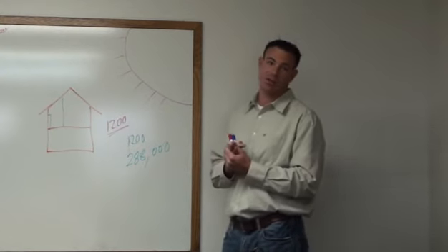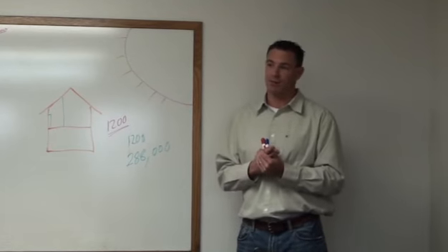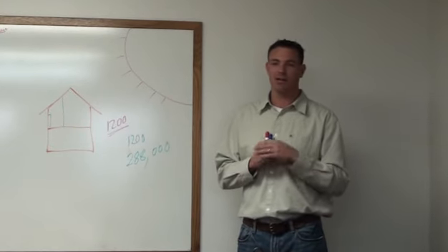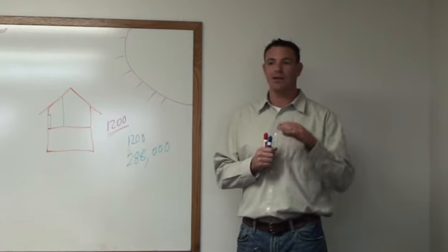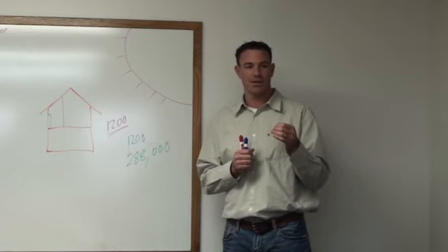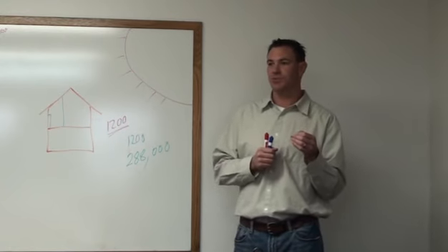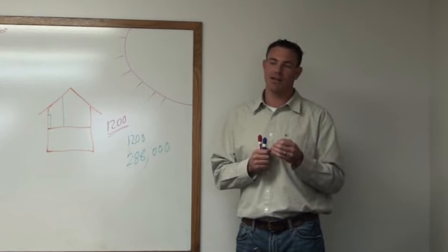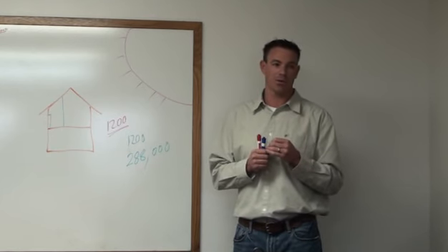Something else that's extremely important with air conditioning is airflow. And it'll probably be your biggest concern when you're talking to customers about airflow, is there's a little washable, removable filter that goes on the unit. And I would say that filter should be cleaned once a month. If that filter gets dirty, the air conditioning unit is not going to work properly.